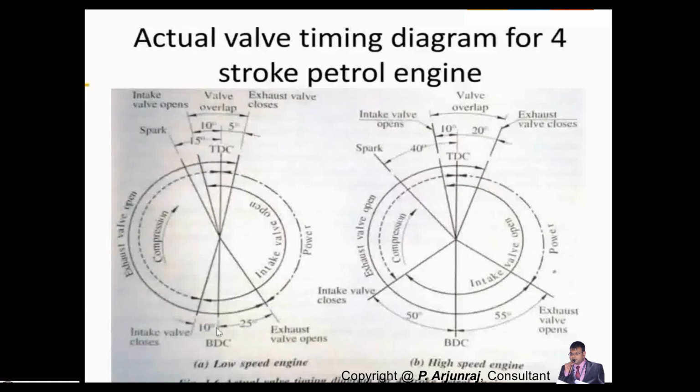You always need to remember one thing: the inlet valve opens where the air enters, in the case of diesel, and in the case of the petrol engine, the air and fuel mixture. The inlet valve opens. This is the first process. So the first process is the inlet valve opens. When the inlet valve opens, the air fuel mixture comes into the combustion chamber. So this is the TDC.